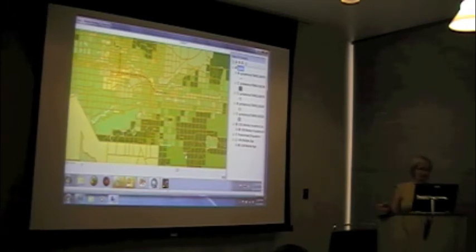So ideally, if we design zones, we want people with similar travel behavior to be in the same zone. So ideally, you want high-income people in one analysis zone and low-income people in another analysis zone. It's a rare situation where there'll be proximity between expensive and affordable neighborhoods. But if there is, you don't want an analysis zone where half the people are high income and the other half low income, because they have different behavior and that blurs the result of the modeling.